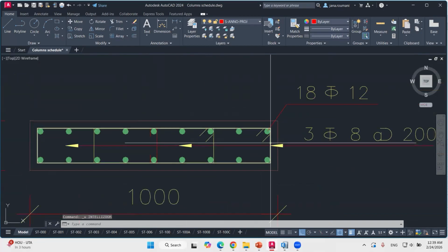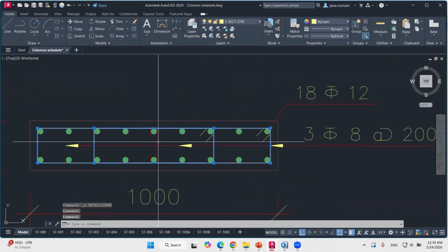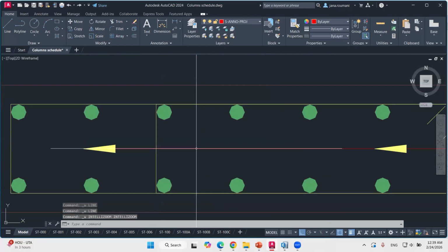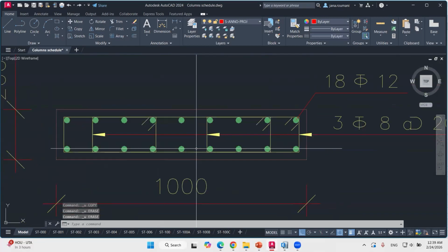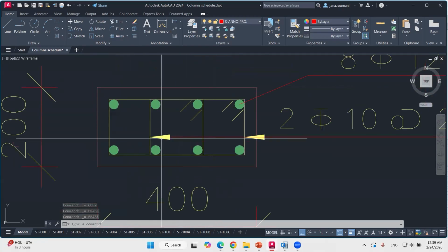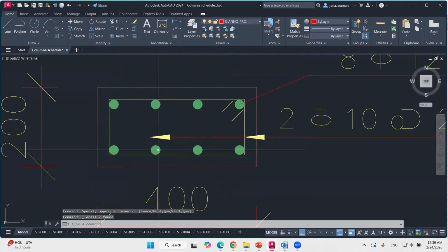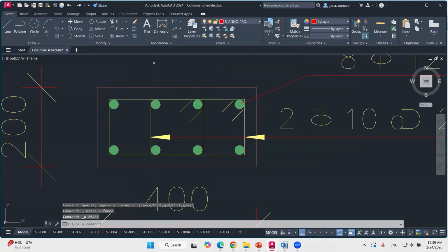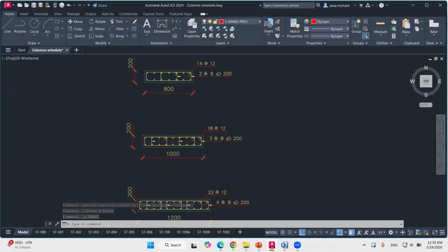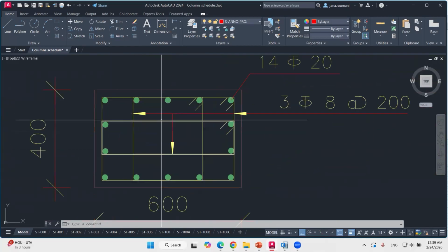And of course, here we need to mention that we now have 2 stirrups instead of 3 plus 1 hook. So here, in order to keep it symmetric, and because if we don't have this, we will have 2 bars unconfined, we don't have any other options. Same one here, same one here. Okay, we consider this one.